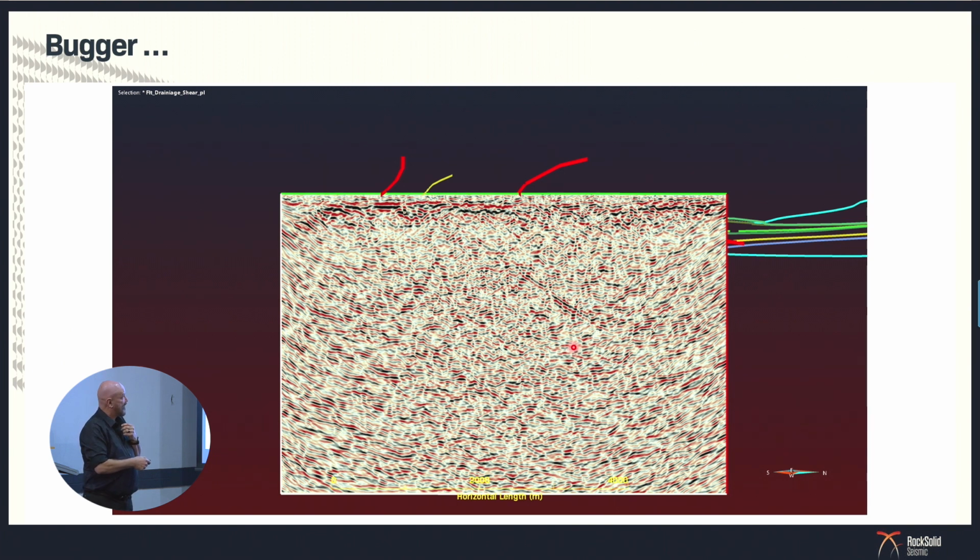something that comes down through there, and those are the shears that were mapped. And this one here is not actually mapped, but it's a shear that's occupying a drainage system. So that matches up with something through there, and that one matches up there. Those two things I can say, well, they're probably faults now. And I've got something here that extends through, so the faults are pretty close to what the stratigraphy is. I'm not sure what's going on here at all.